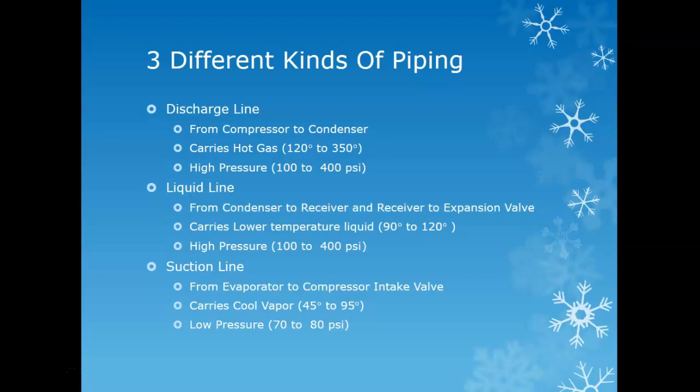Put it this way, if you get a hole in that, do not ever put your hand near that. That is not boiling water. That is steam. That is going to take your hand off. That is second to third degree burns. Okay? If you ever see a discharge line that is ruptured or has some sort of a hole in it, walk away, call somebody that can deal with it, or turn off where you know the pressure is going to be. Because that hot gas is not going to be a friend of yours.